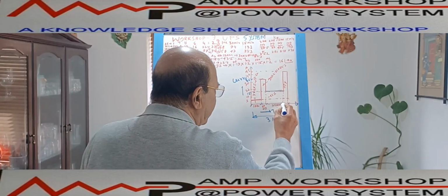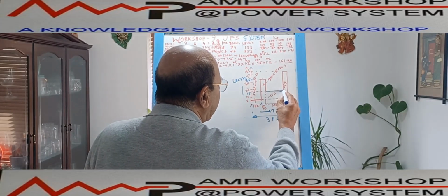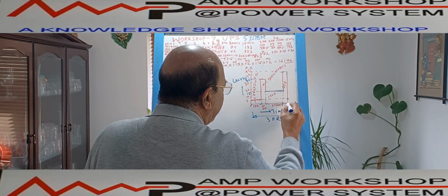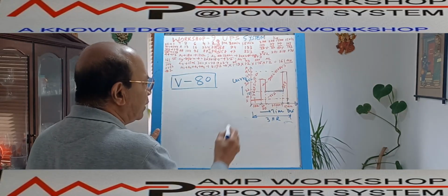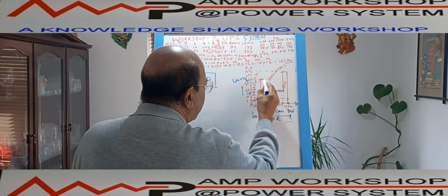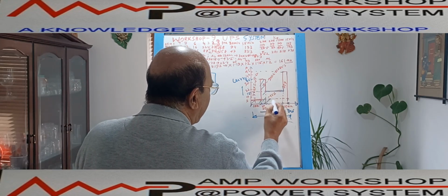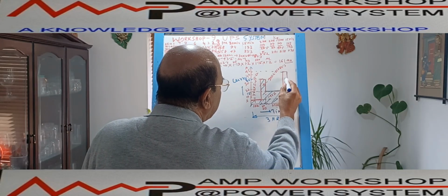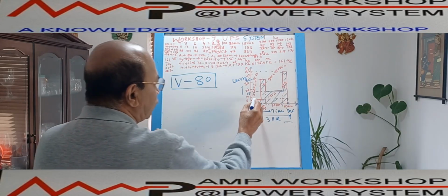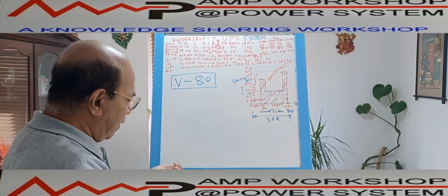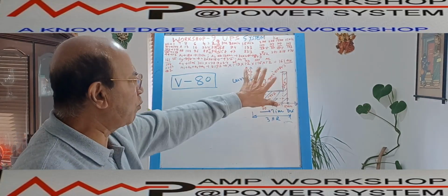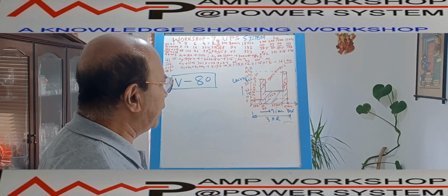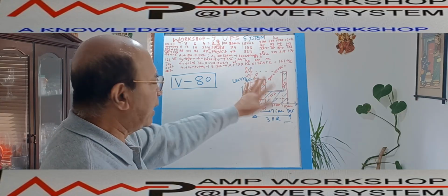After 75 minutes, this 15 ampere current suddenly increases to 45 ampere, and then the period is over. So this is the load profile. If you draw the profile of the current given by the battery, the hatched portion below is the area of the current profile. Now to calculate the ampere hour for this current, the current is not constant.